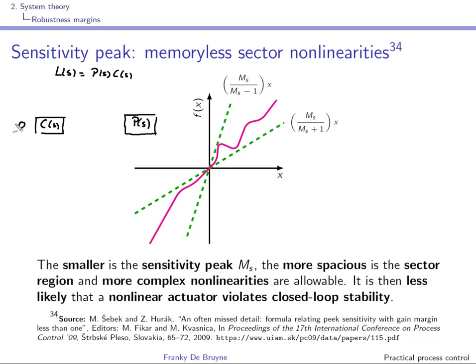And here we have the set point, here PV, and here is the feedback part. We have a minus and here a plus. This is the error, and here we have MV, and this is the loop gain.